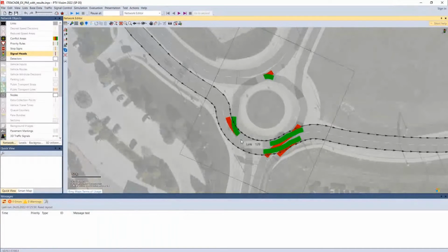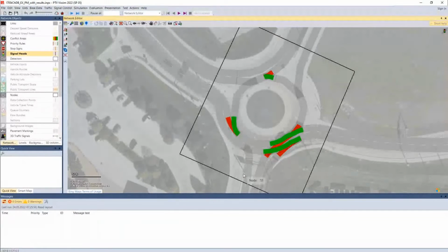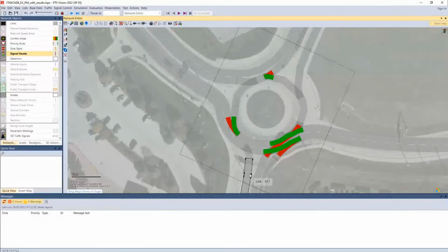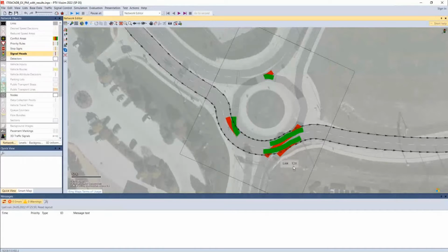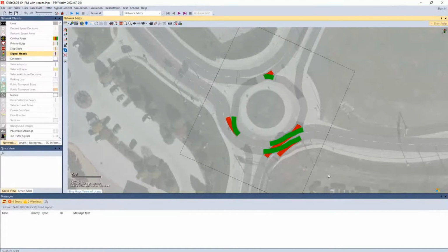So they're not having, because you don't want vehicles making lane changes within the roundabout, right? So this might be something like you have a striped gore point and then you have a link just jutting through and they have to cross both and they'd have to yield to both. So that's something where you want to look out for here, where we're looking at the movement of the vehicles. So kind of taking your mind away from just the lane configurations for a second.